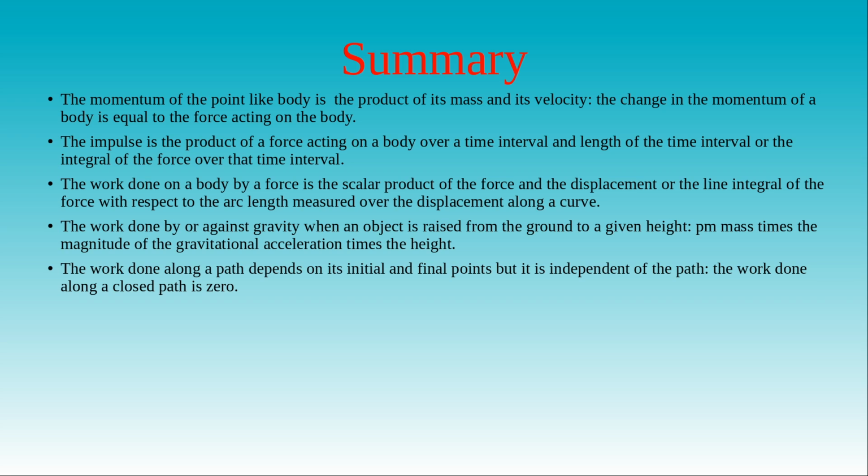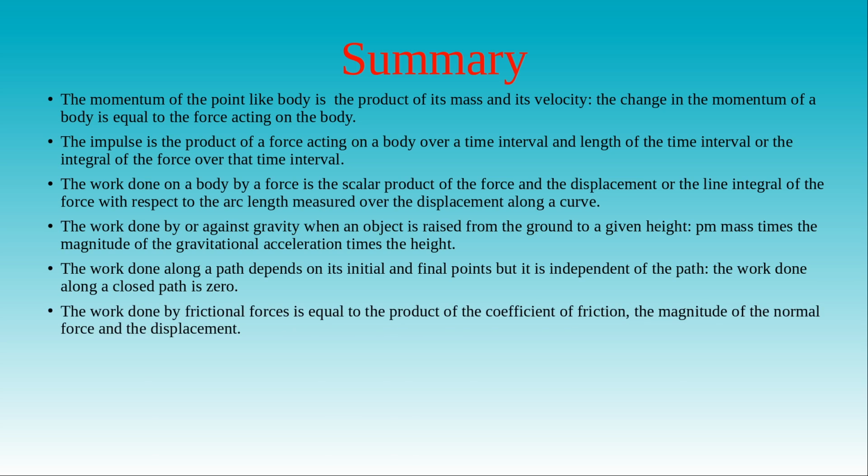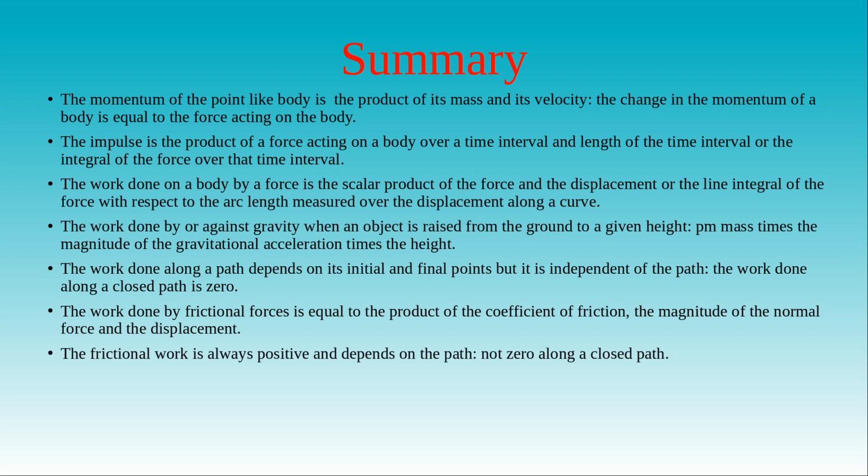In the next example, we determined the work done by frictional forces for a body sliding over a surface at a constant velocity. We showed that this work is equal to the product of the coefficient of friction, the magnitude of the normal force acting on the contact surfaces and the displacement of the body. We also saw that the frictional work is always positive, and the work done on a body brought along a curve over a surface depends not only on the initial and the final points but also the curve itself. In other words, the work done against the frictional force along any closed curve is not zero.